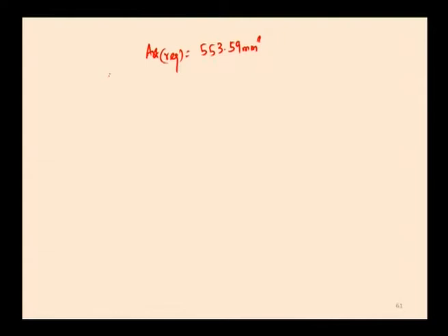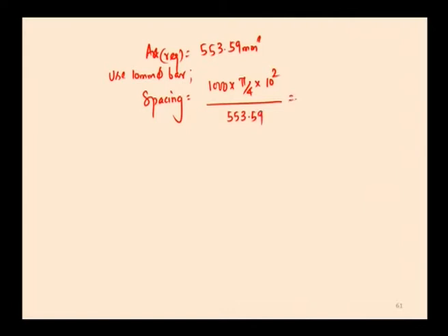I am finding the spacing of reinforcement, that is for 1 meter width of the slab, 1 meter into area of 1 bar divided by AST required, it is 141.87 millimeter. So, hence I am adopting, before that I need to check